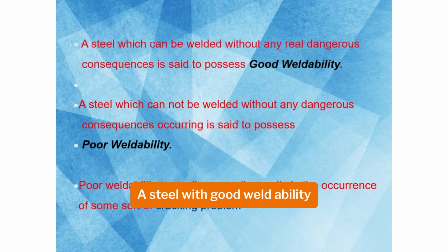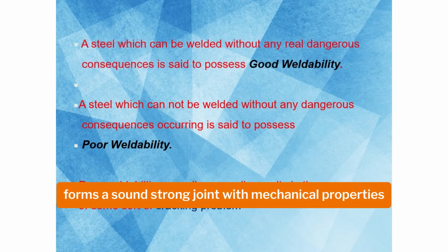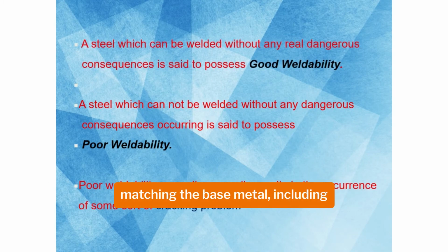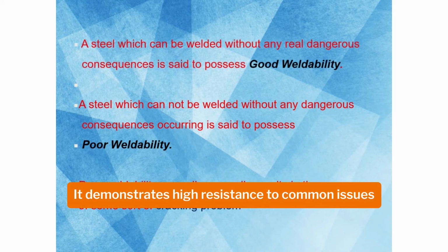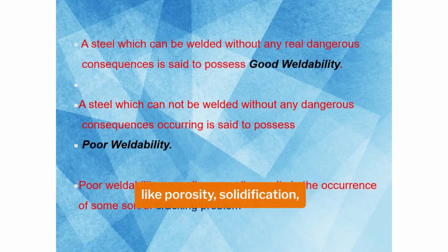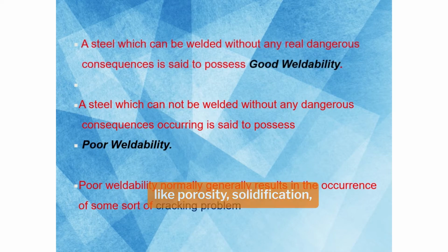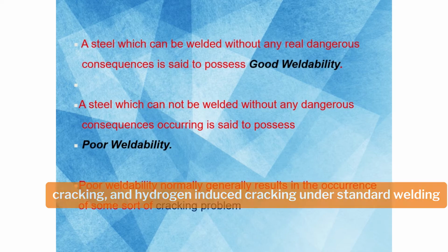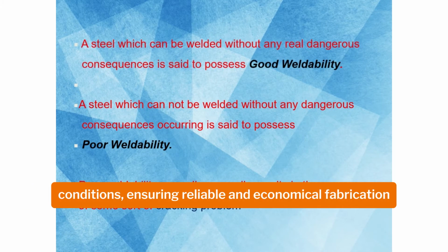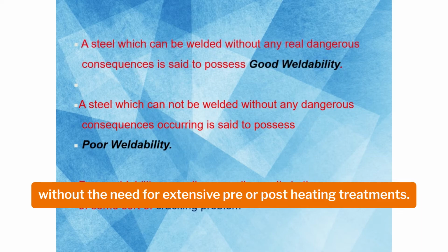A steel with good weldability forms a sound, strong joint with mechanical properties matching the base metal, including consistent strength and toughness. It demonstrates high resistance to common issues like porosity, solidification cracking, and hydrogen-induced cracking under standard welding conditions, ensuring reliable and economical fabrication without the need for extensive pre- or post-heating treatments.